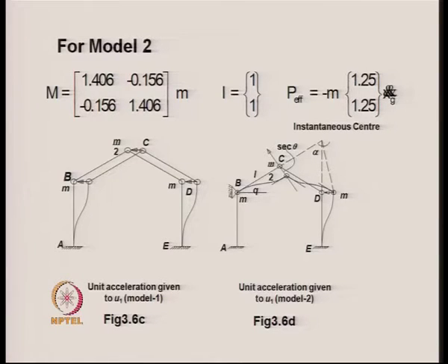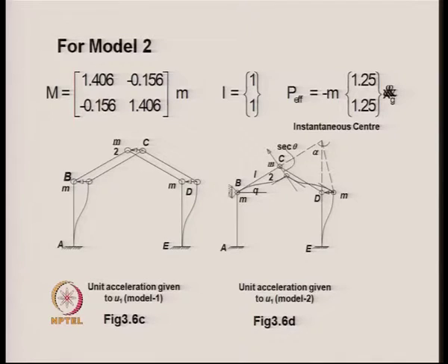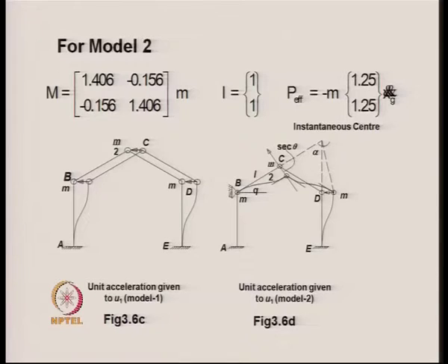So, that is how one can calculate the mass matrices for the different types of degrees of freedom that can be chosen for a pitch roof portal frame. And there could be structures where this mass matrix, even for the lumped mass case, could be fully populated.